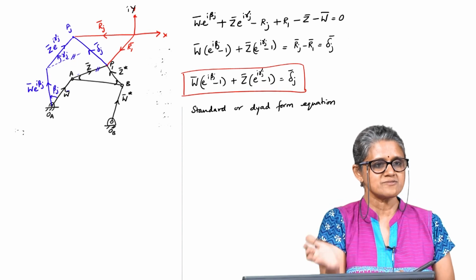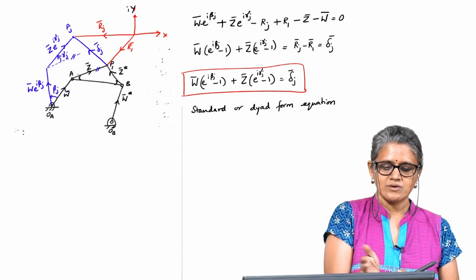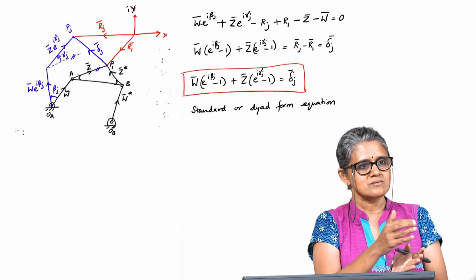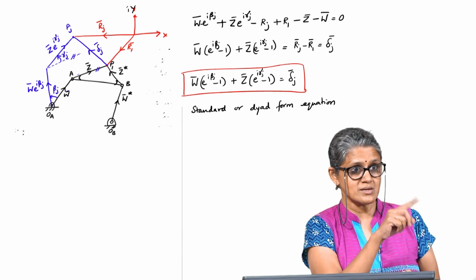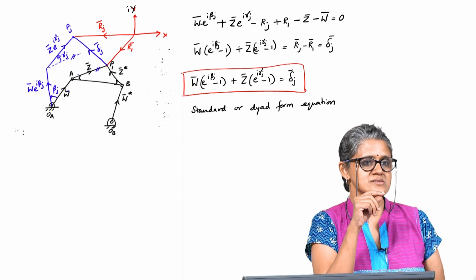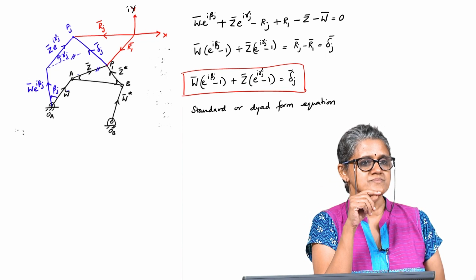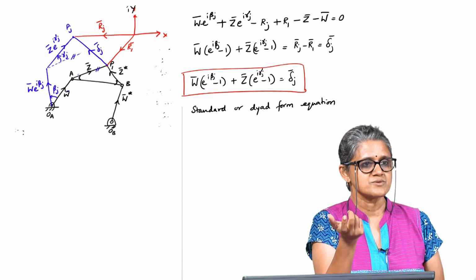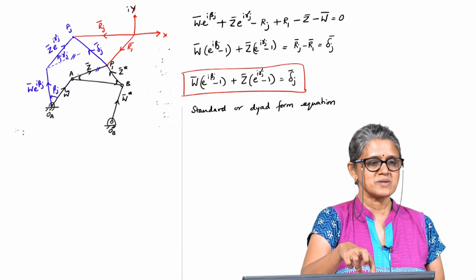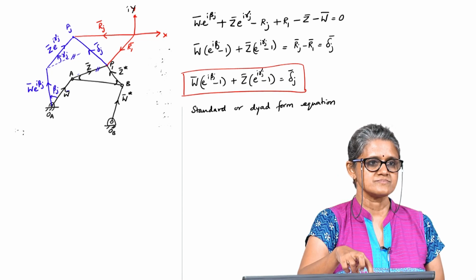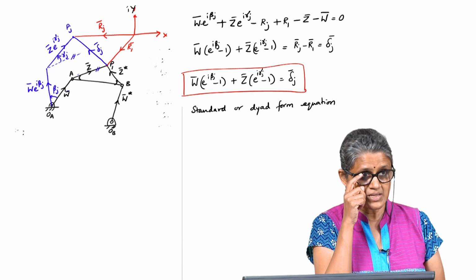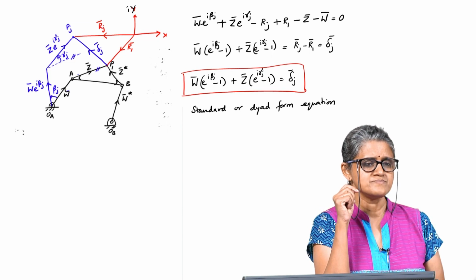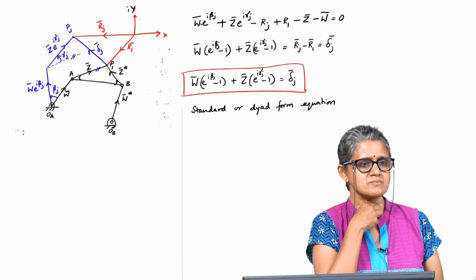Okay, then we will also look at function generation, for W and Z with certain angles, W star, Z star, what the angle should be, so that you can do the synthesis of your linkage. Similarly, for motion generation, this displacement vector will be given. This basically shows the displacement of the point P1 to the position Pj.